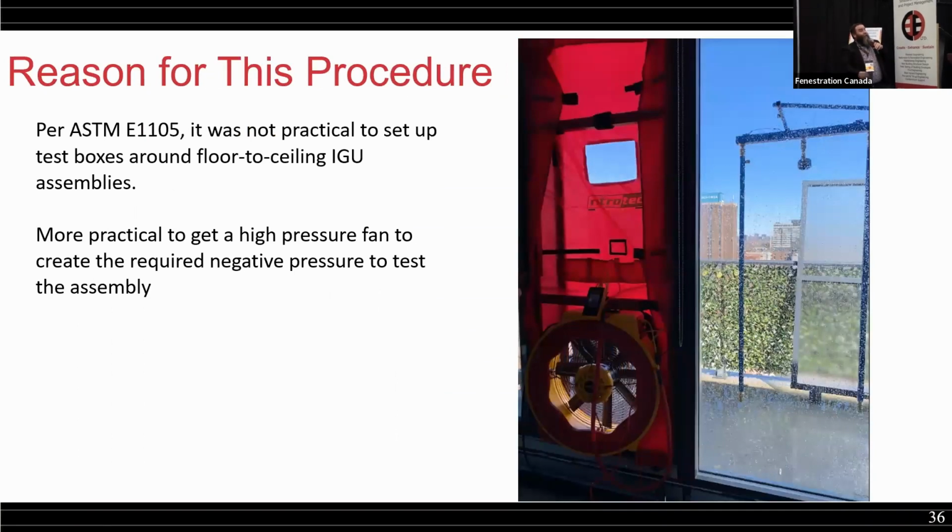Just one question. Ideally, you measure the pressure difference between the outside of the building and the test chamber. Whereas what most do is they measure the pressure difference between the test chamber and the room pressure. So the ideal is outdoors. That is the correct source. If you're going to use the corridor, you either have to justify that and adjust for it, look at the different pressures, or generally speaking, if you arrange in advance, you can get the corridor open to outdoor pressure. That'd be the ideal solution. But yes, it can be a problem, but it can also be addressed.